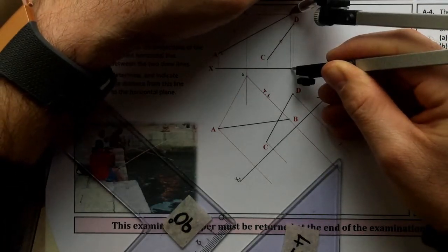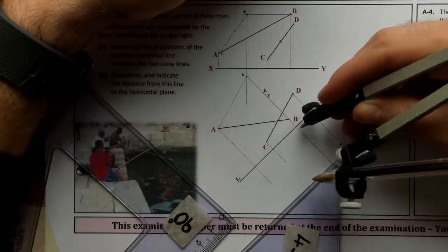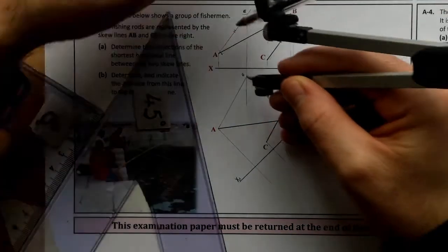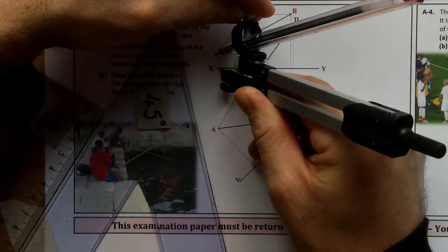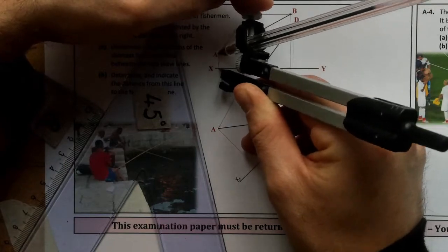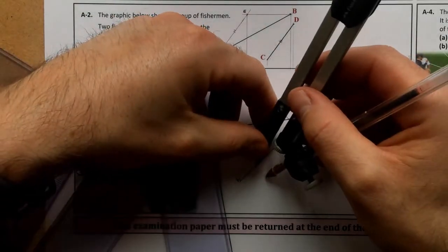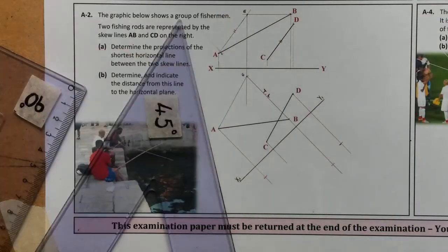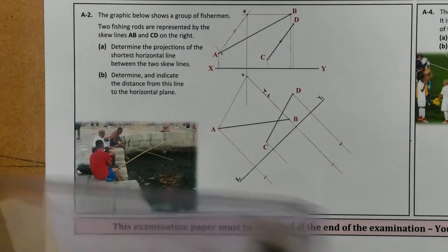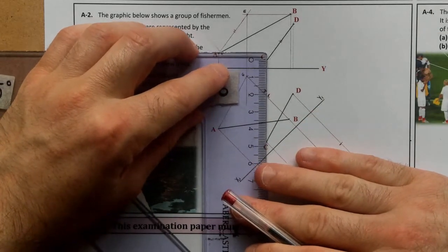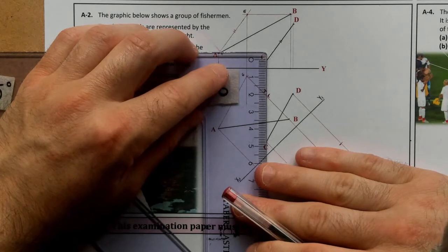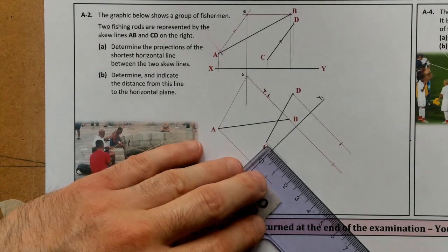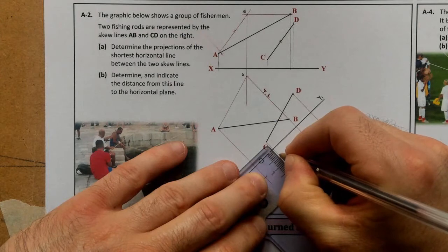Likewise with the B, out to B, follow it here in plan, out to your X and Y1, and then same with A. And follow A out, and finally C. And unfortunately my compass is with the pen attachment, it's a little bit short, so I'm just going to measure it and just try and get, I can see there it's working out about 5 millimeters, just slightly 4 point something, so try and be as accurate as I can with this. So marking that there, I'm happy with that actually.